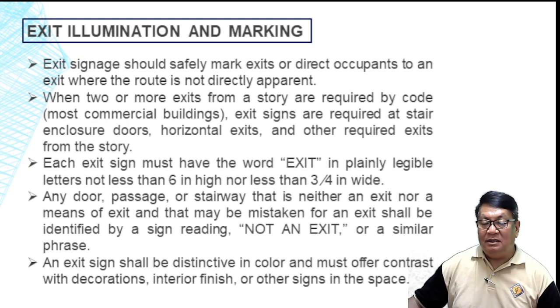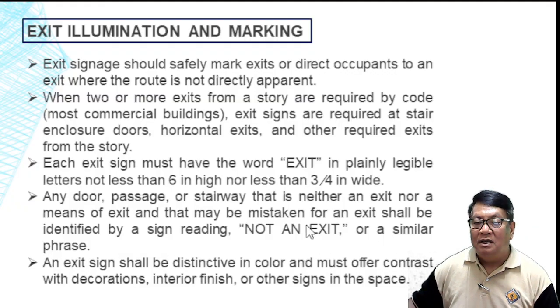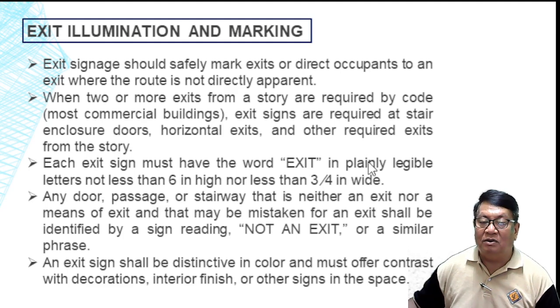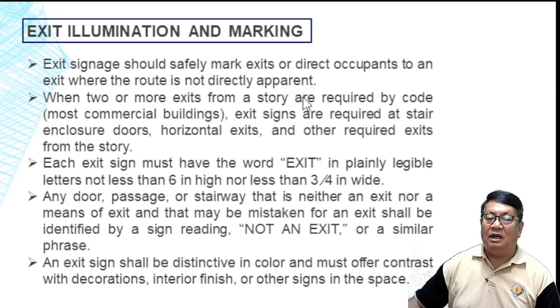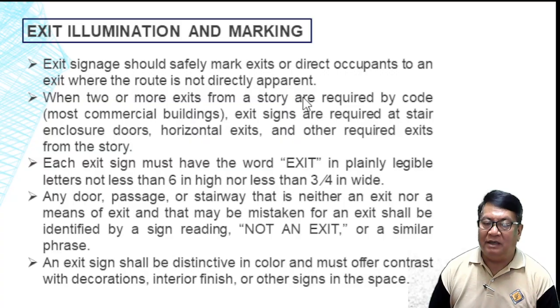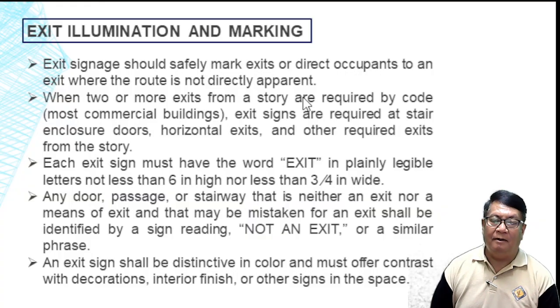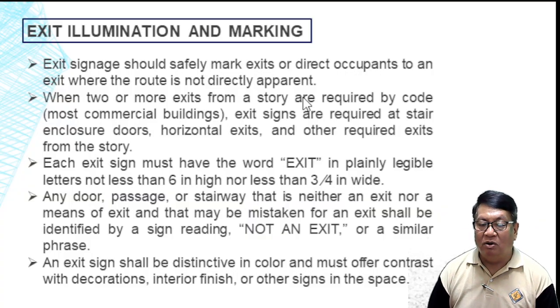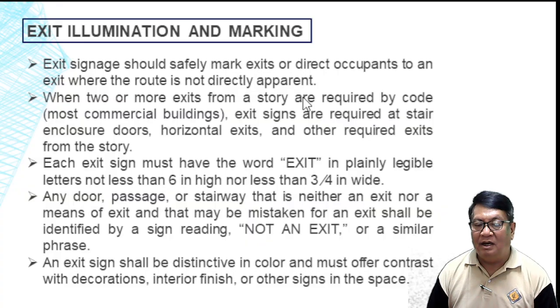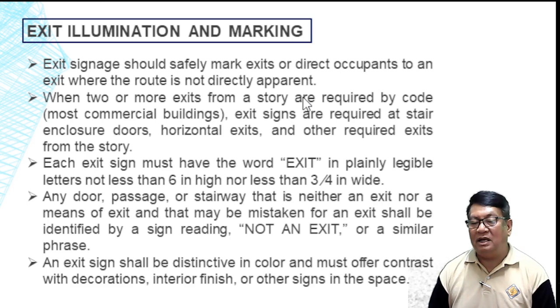Exit illumination and markings. Exit signage should simply mark exits or direct occupants to an exit where the route is not directly apparent. So we have to consider not only exit signages but also the directive markings, especially showing the place that we should go if we have calamities like earthquakes or landslides, and so on and so forth.